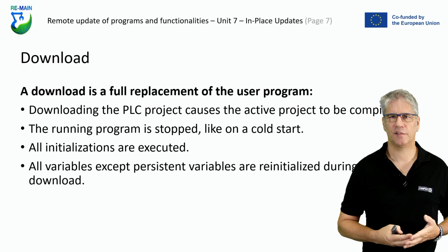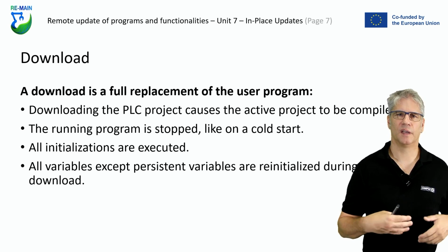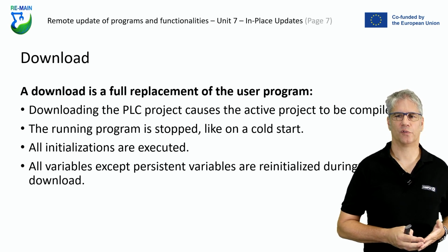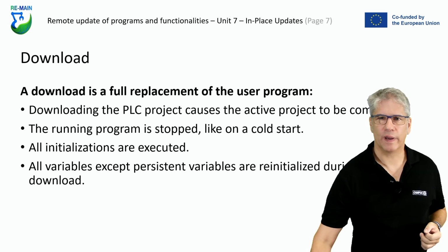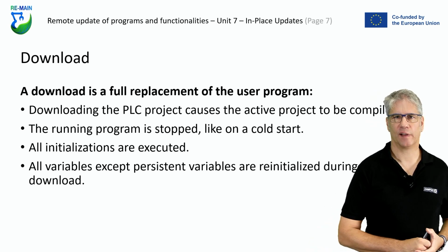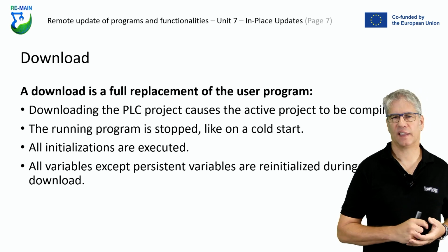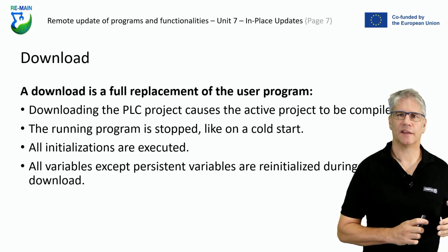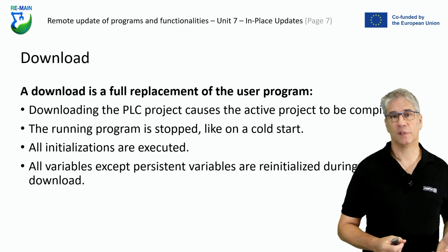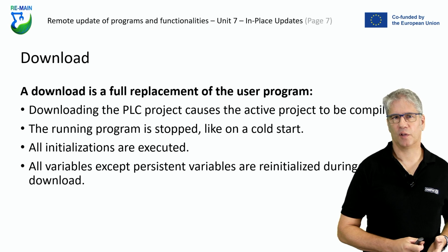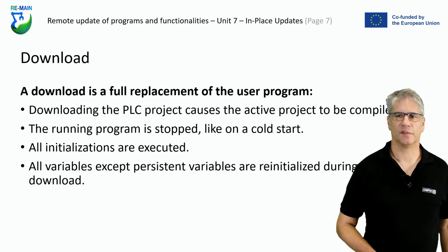If you change operating system, if you change more than this or do a factory reset, then of course also the retained variables are gone, which means that some parameters could be lost. So you have to be aware that if you create a program, you should be able to provide mechanisms where you can reinitialize those values. For example, the zero setting of some motors or similar things that are stored in retained variables, so persistent variables on the PLC. But if you delete them, the machine may not be able to start because some parameters are missing.